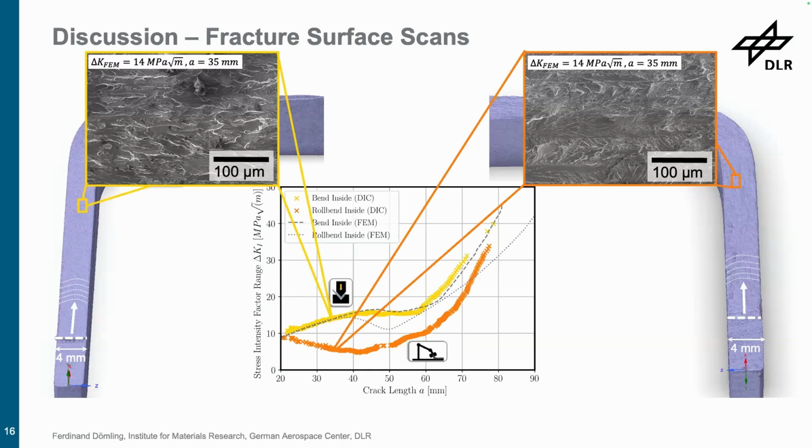We also know what we get from our evaluation via the interaction integral on the DSC. And we can get the exact information of the crack surface, and then do SEM characterization and check out the crack surface. So we see here our crack surface compared to that.